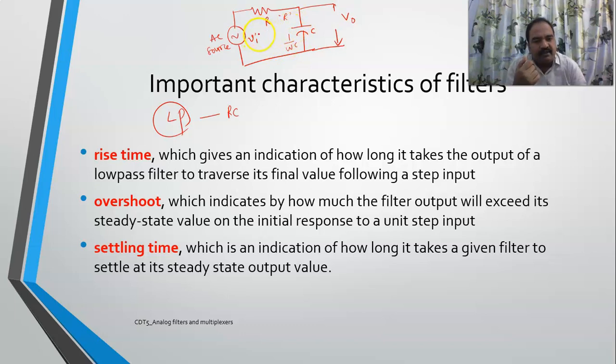So whenever you are seeing this system, if you carefully see, at lower frequencies, this value is independent of frequency, the impedance offered, whereas for this one, since the value is low, the impedance offered is high. So the equivalent impedance, you will get some R plus 1 by j omega C, right? This is your impedance. Sorry, R minus j by omega C.